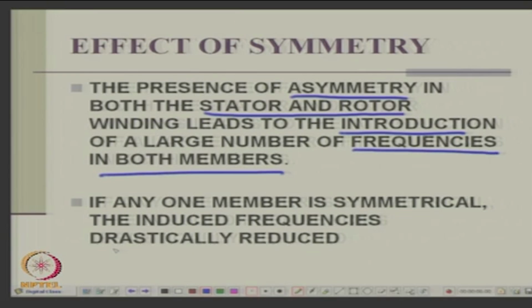Normal induction motor, both are symmetrical. How many frequencies do you have? In a normal induction motor, 3 phase stator, 3 phase rotor, how many frequencies are there in the stator? Only one, f only, 50 hertz only, you are happy. How many in the rotor? One only, slip frequency, you are very comfortable. But you have a problem if the supply voltage becomes unbalanced, then you have 2 frequencies in the rotor. So long as supply is balanced, there is no problem.